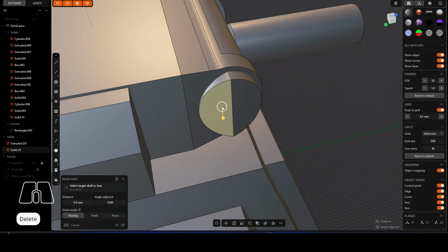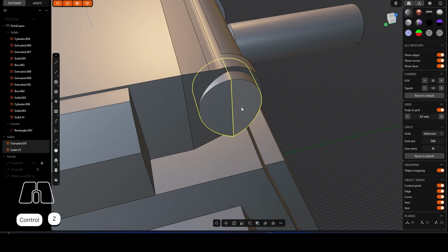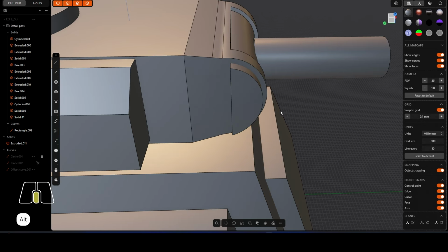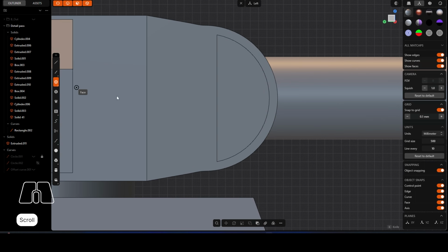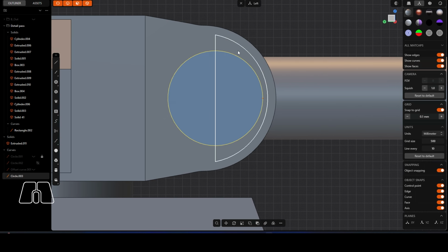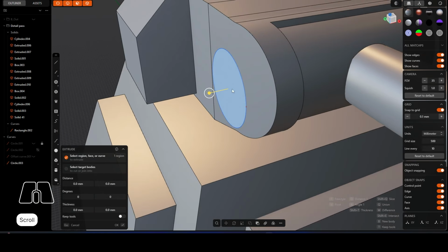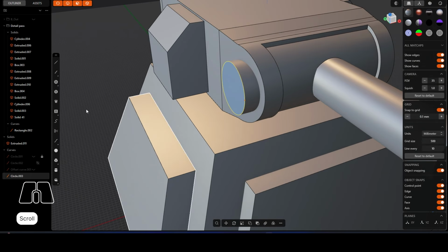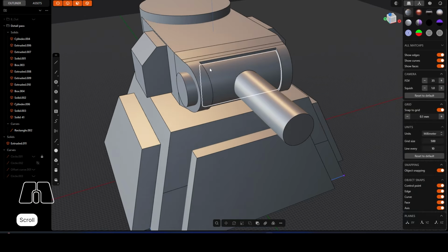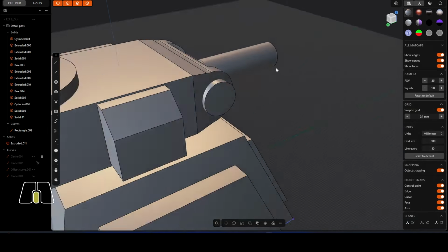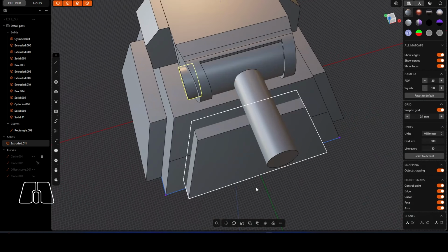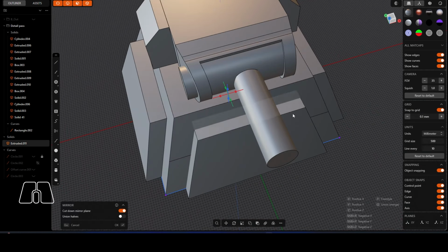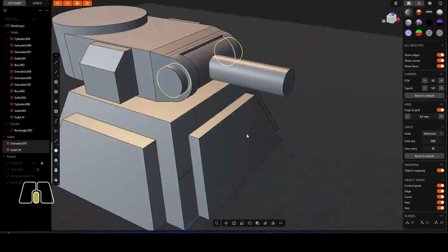So in that instance, what we should be able to do is, if we grab this now, we should be able to get a center point here, and that's going to be our circle. I can get rid of that now, grab this, extrude it in like so, and then we've got that center point sort of aligned up. And again, you don't have to do this, you can eyeball it, but for me, I'm a bit of a mega geek when it comes to this stuff, so I do like my parts to be believable and line up.